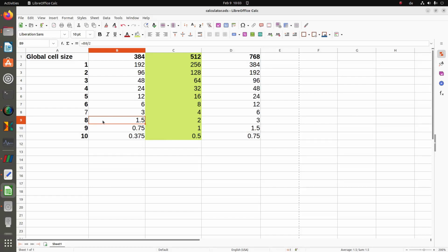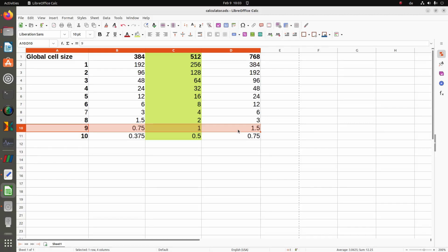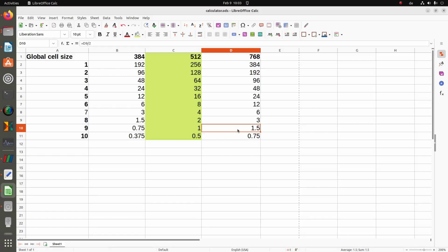In the first case, it can happen that cells at the flaps with the small gaps will be destroyed. In the second case, the number of cells may again become too large. I will therefore switch off refinement box 3 to save the cells there.